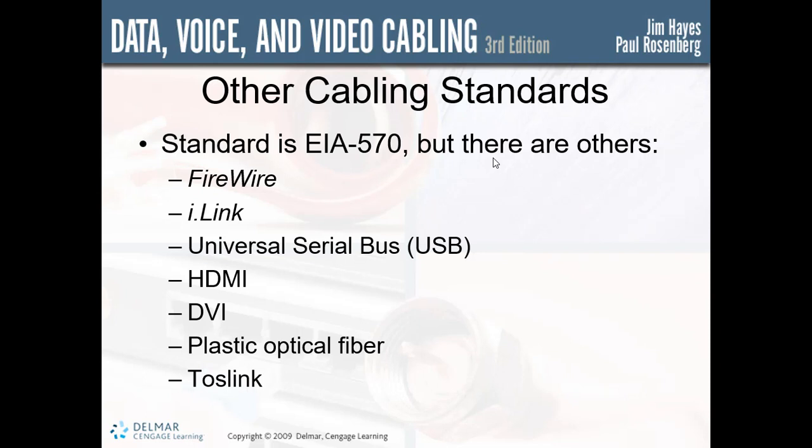The IEEE 1394, also known as Firewire, is typically used as an audio-video bus for interconnecting devices. It is a high-end entertainment bus, for which digital cameras or computers form entertainment networks. We can also do it over USB, which is occasionally mentioned as a networking technology for homes. It can transmit 1.5 to 12 meg speed over copper cabling. It can go up to 3 meters, in some cases, up to 5 meters. Home theater installations often require digital connections to a TV, digital video, HDMI, whatever.